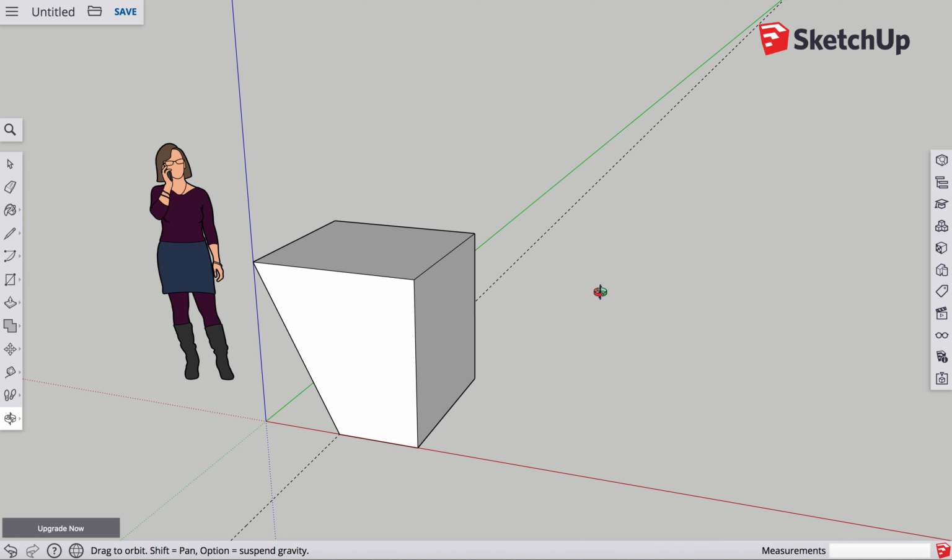So, that last one we moved one parameter of the object. This time I'm going to carve it. Okay, so I'm going to do a tangent here and carve a piece off the side of it. So we're going to go into arc, and I want the one which is 3, where you do 2 ends of the arc and then the radius. So I'll pick that one, and I'm going to go on the edge there, click, and then take it over to here.